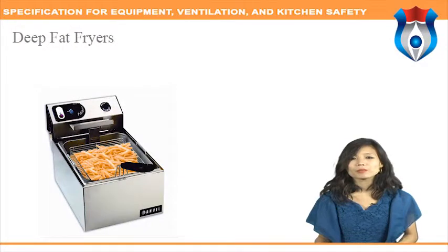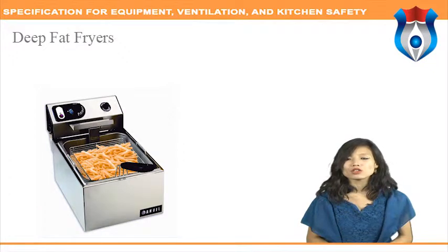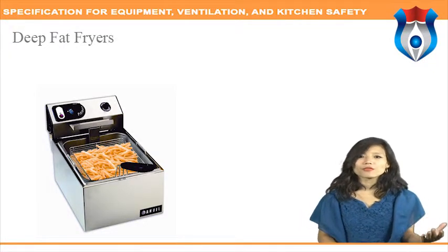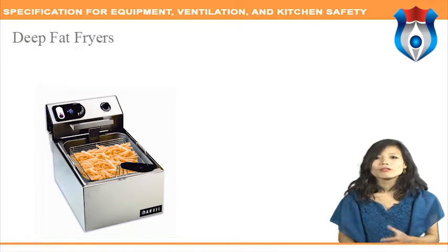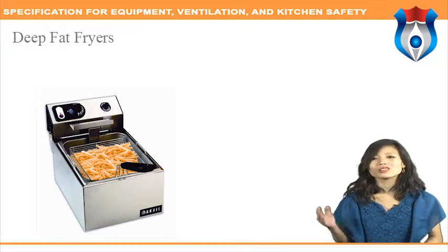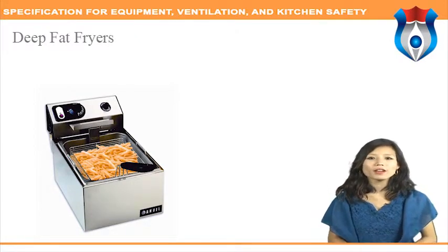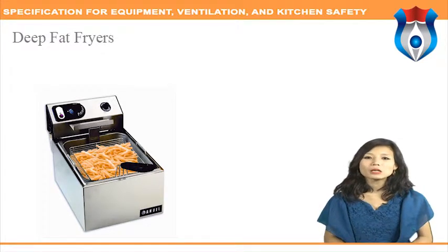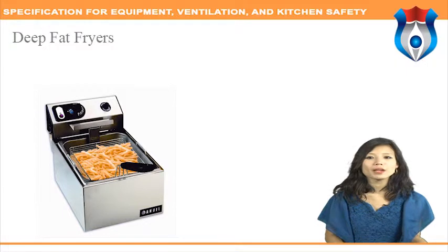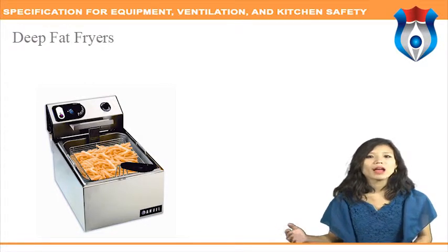Deep fat fryers. Deep fat fryers are available in a variety of types, capacities and degrees of automatic operation desired. The productive capacity of a fryer is related to the liters of fat in the fryer, the heat input and the cooking time required for various foods. Typical design of fryers is based on a fat to food ratio of 6:1. This indicates that each kg of food to be fried requires 6 liters of oil or fat in the deep fat fryer. Conventional fryers are tailor-made to the requirements of the client in various capacities, such as half liter, 1 liter, 3, 5, 7 and so on.